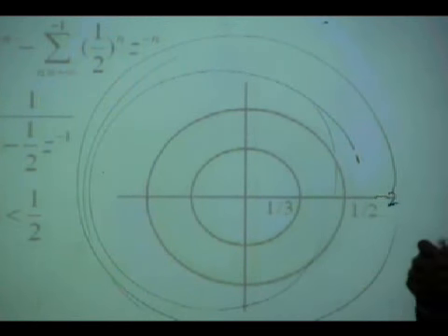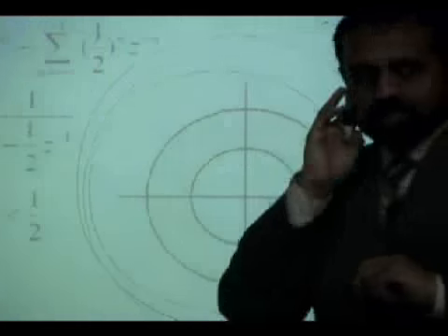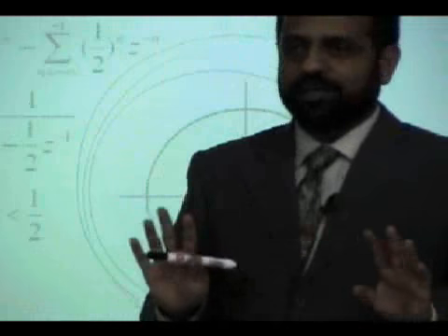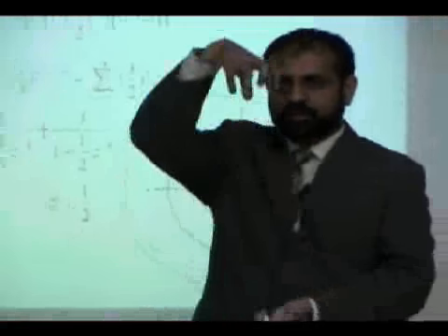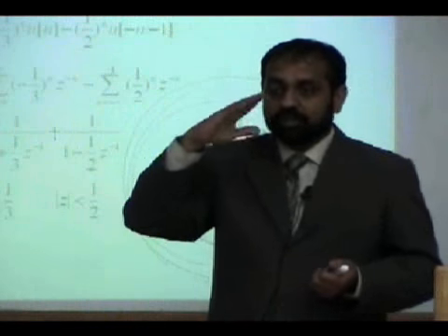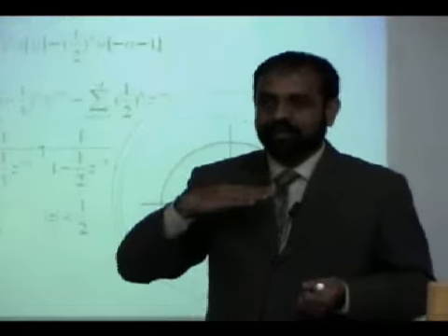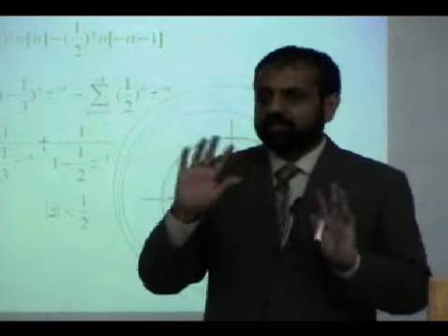Only stability. The question and confusion is what a unit circle is doing here. Nothing. Unit circle is a test. So you make the region of convergence, draw the unit circle, and check whether the unit circle is in the shaded region or not. If it is, you say system is stable. If it is not, you say system is not stable. Let me give you an example, and that will help you to understand it better.